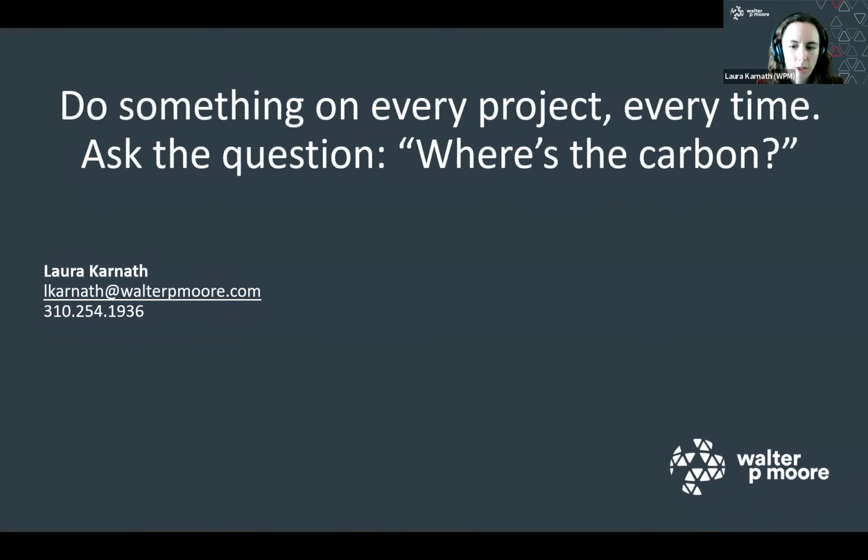So when you're setting up the whole building LCA, if you're comparing alternatives, you as the LCA practitioner are going to set up, say, mineral wool versus spray foam, and I'm going to make sure that they have equivalent R value when I set up the LCA model, but the tool isn't necessarily going to do that for you automatically. That's why it's important as an LCA practitioner to make sure that you are using functionally equivalent systems.